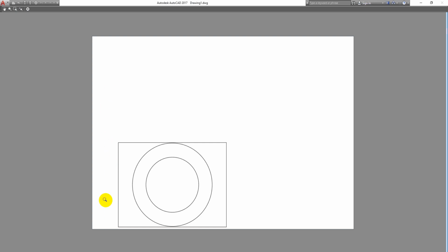That is the reason why we are leaving this space here. Okay, so there has to be a margin. So if it is for say A0 size or A1 size and all, you might not require that, but still it is a good practice to leave a small margin there. It is not to take too much space and leave it for margin, but a very nominal margin can be provided towards the left side. That is always good.